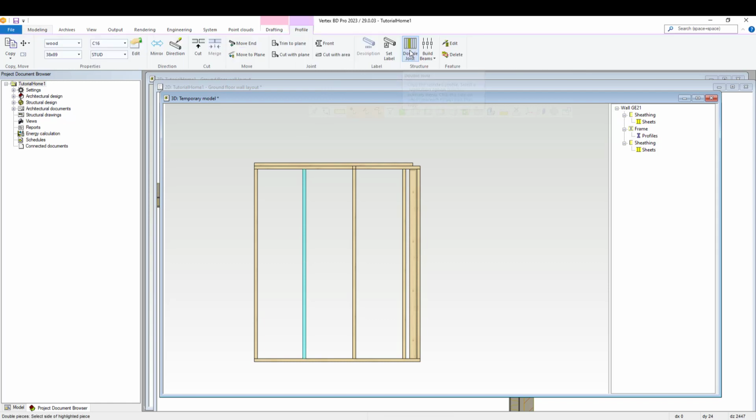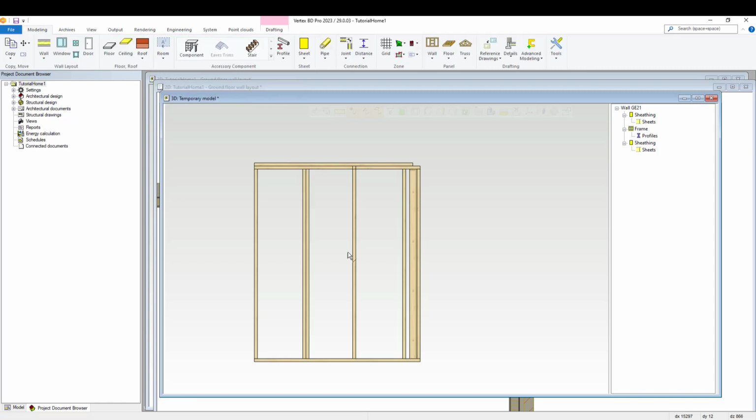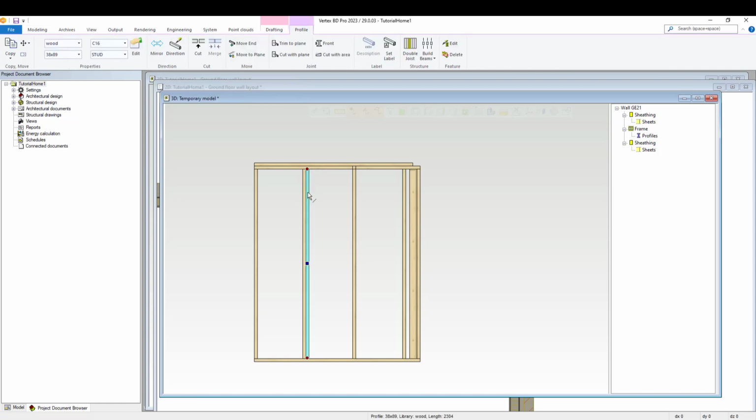One very useful feature is the double joist function. Again, this has its own set of options where we can toggle if the double is mirrored, if the center of the two joists is moved to the current center point of the single joist, and if there is any tolerance between them. Once defined, simply click on whichever side you wish to mirror to.